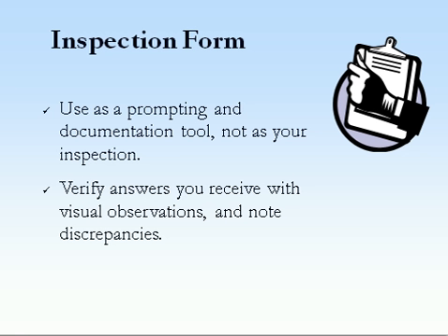You also want to know where the wastewater is generated within the industry, and talk to the industry about what kind of pretreatment equipment they might have, especially if it's changed or if they're thinking about changing it. If they've got flow diagrams, ask them for a copy of it. That's a great thing to have.